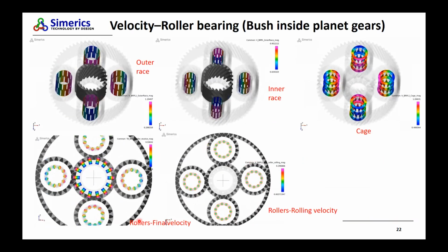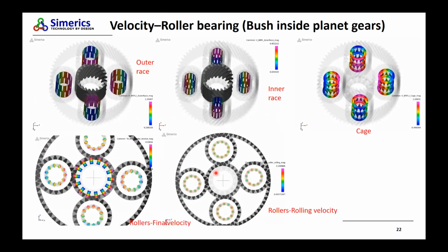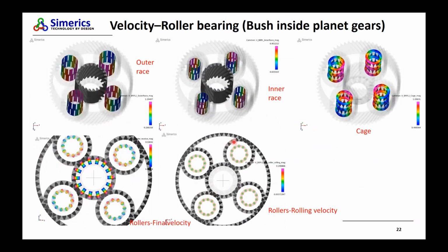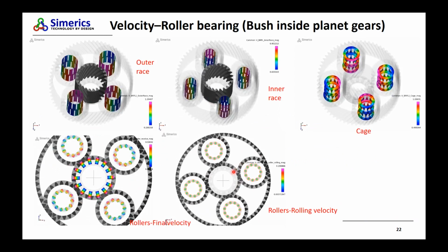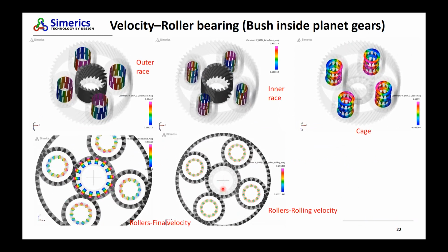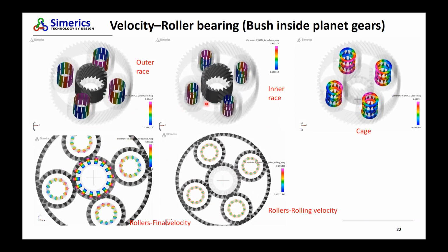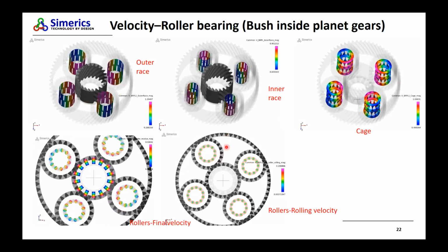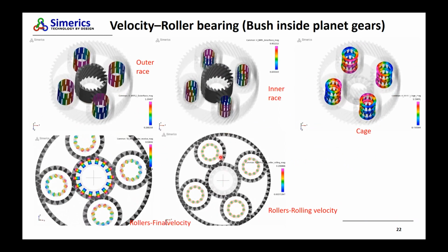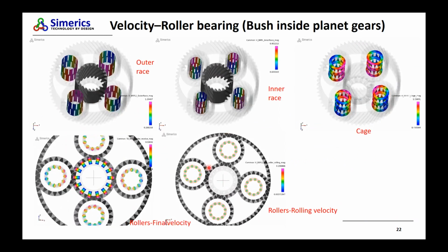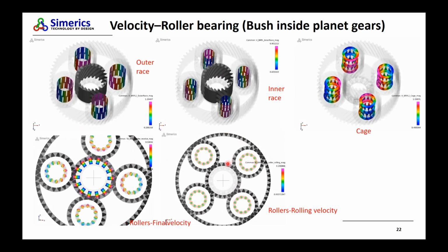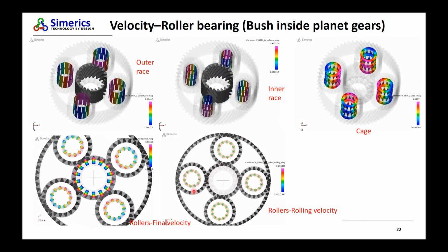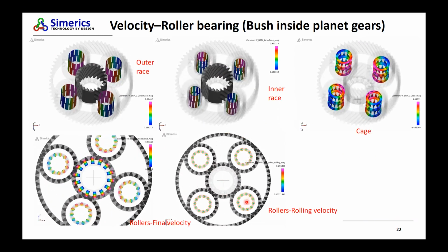In terms of capturing all intricate solid movements, that's one thing that the intermeshing can help us do. For example, we are showing an animation of the planetary gear system, which has the gearbox inside of it. You have these needle bearings, so we're looking at the lubrication of this entire system. We can capture these clearances for both the gears as well as the bearings.